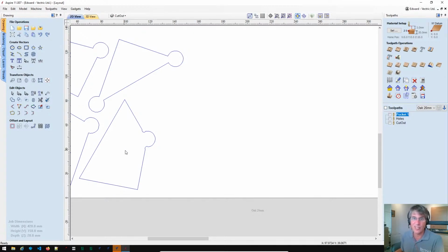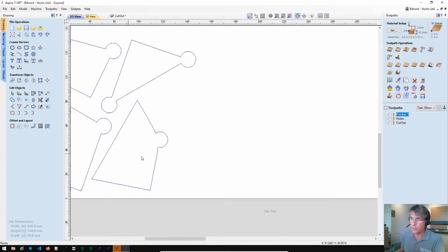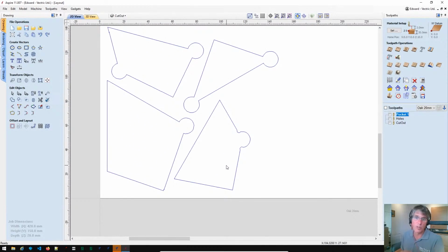And actually, it took about a minute, 2 minutes, and probably you get a neater job. So I just chiseled out effectively those little radii manually as a post-production process. For a one-off job like this, that's the lesser of evils, I suspect, and it's probably a slightly more sightly final result if you want to do it that way. But this is how you would go about filleting it if you needed to. And if you were mass producing and you wanted to minimize your finishing, then that's probably what you'd do.